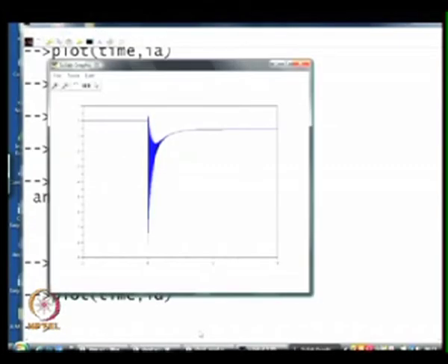The steady state value is only 0.55, but if you look at the initial transient, the peak value goes right up to minus 8. So initially the current is extremely large. This initial few cycles of the fault just after the short circuit has occurred is called a subtransient period of the machine.